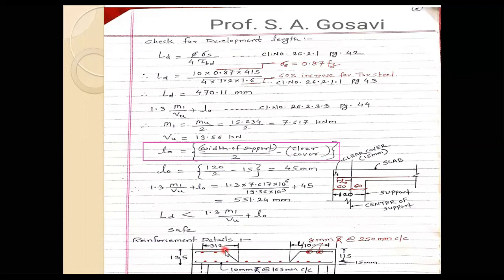It comes over here, then it bends, and this will move in a straight line like this. Okay, this is the bend, and then it will move in a straight line like this. Similarly, a second bar, that is the alternate bent bar, starts from this point. It will move a certain distance, then bend, and then this bar will also move up to this. Okay, so this is your main steel, 10 mm, about 165 mm center to center. The distances I have given over here.